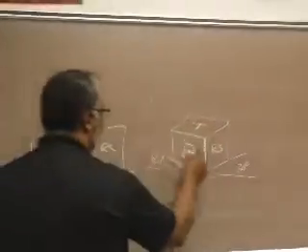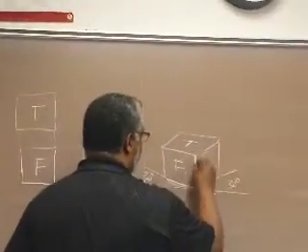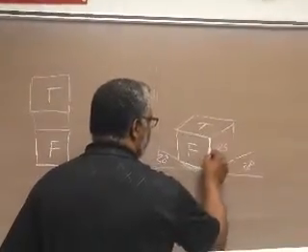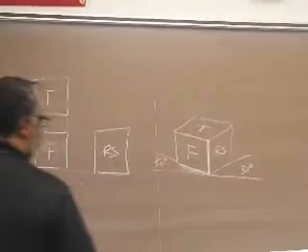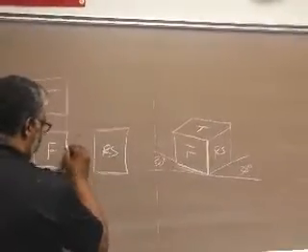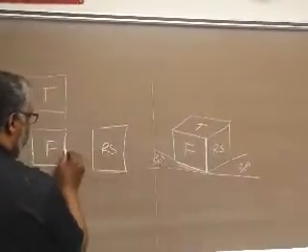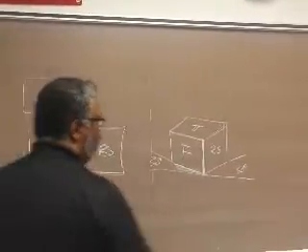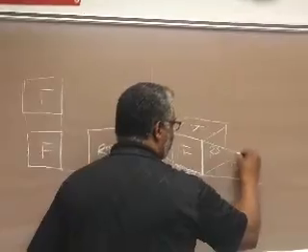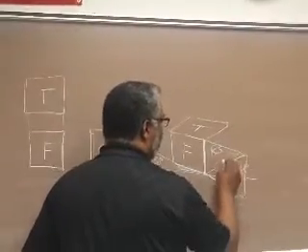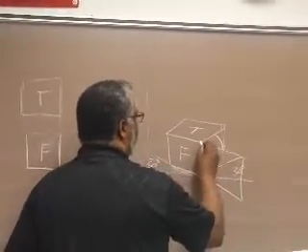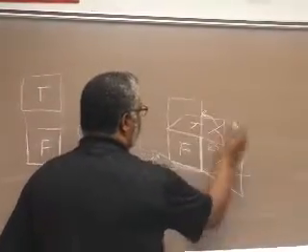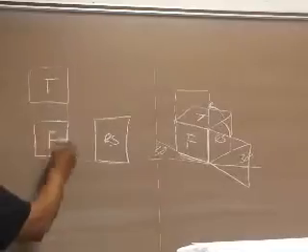So the object, we have an edge facing us, this corner here, this line joins this surface and this surface. So that edge is basically where these two edges coincide together. So this folds out, so you get your right side there, and then this folds up, and you get your top there. So we wind up with top, front, right side.